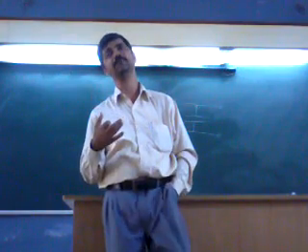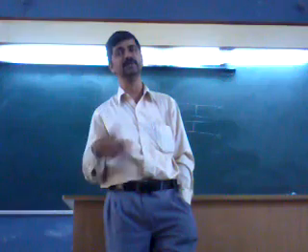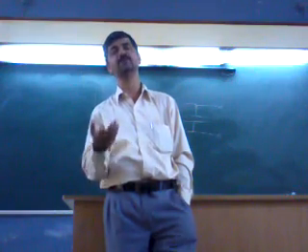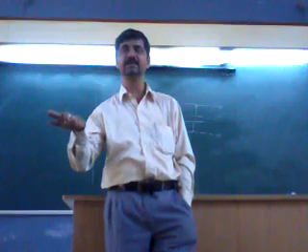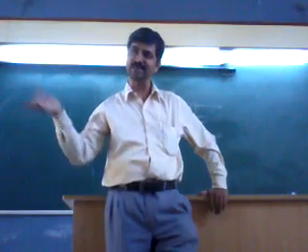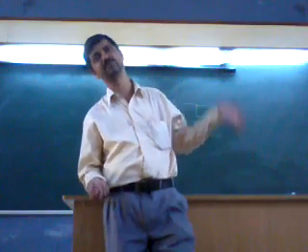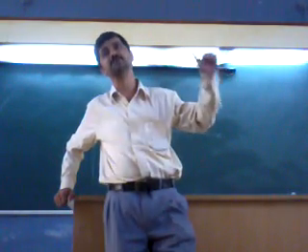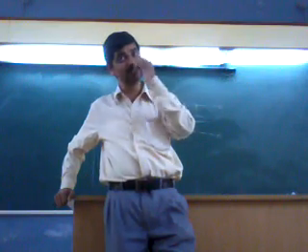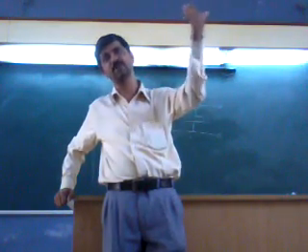It is the ratio of output upon input voltage, V2(t) upon V1(t), if V1(t) is e raised to st. Or the alternative way, any V1(t) you can have. If you find its Laplace transform, it will be V1(s). You will be getting some V2(t), whose Laplace transform is V2(s). And if you take the ratio of V2(s) upon V1(s), that will also be G21(s). Then what does G21(s) indicate? G21(s) is the ratio of output Laplace transform to input Laplace transform.